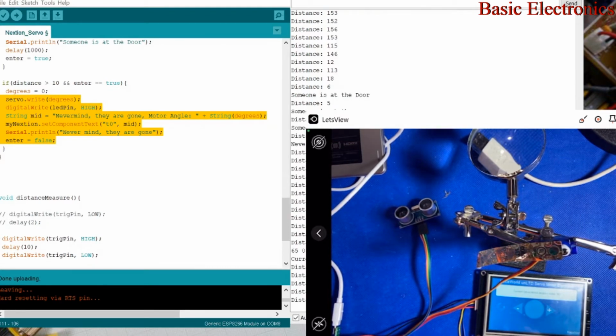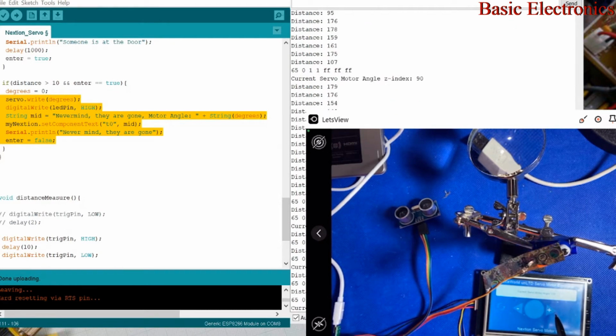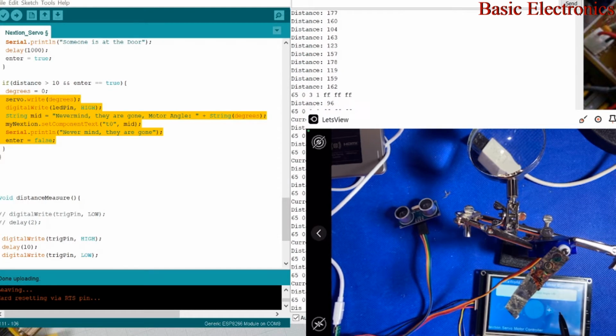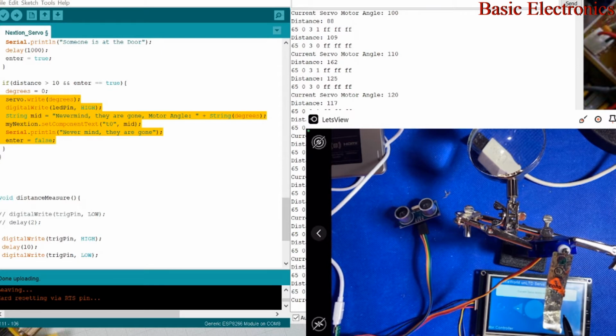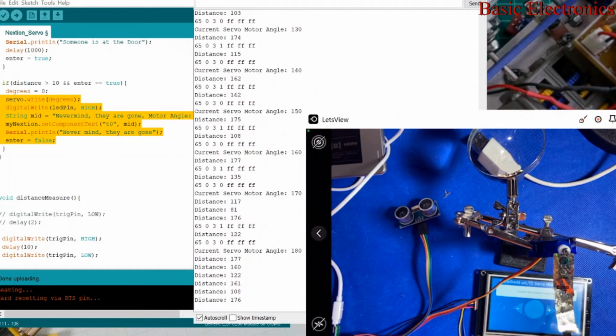And then I can also just press the center button, and you see I'm moving to 90 degrees, and then I'm going to do the plus, so I'm going to do plus 10. Notice the servo motor moving, it goes gradually. And then you can also see that the serial monitor is showing what we're doing right there. So let's just look at it clearly.